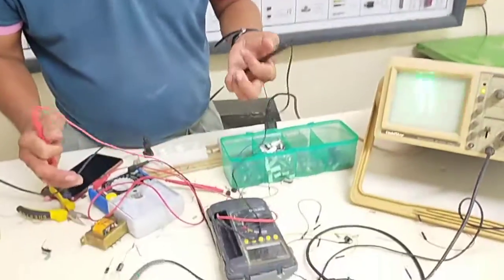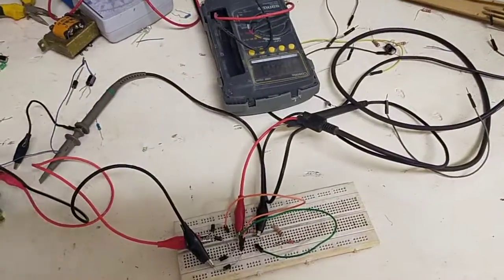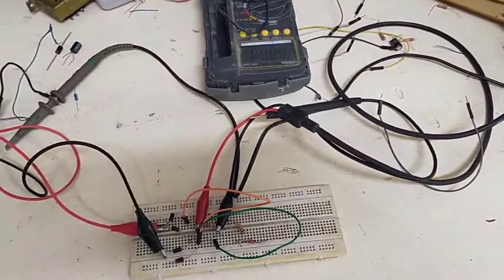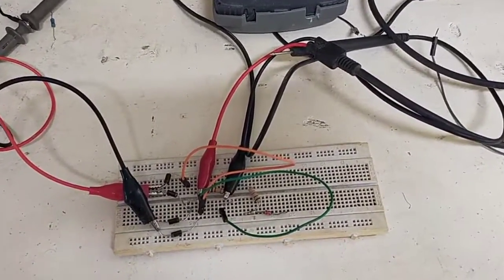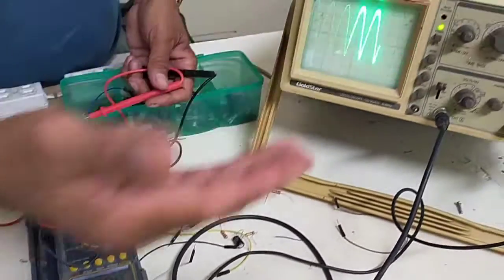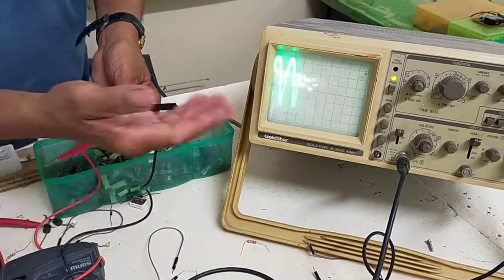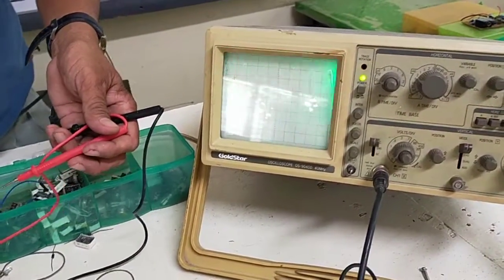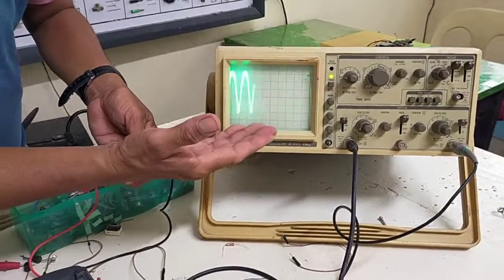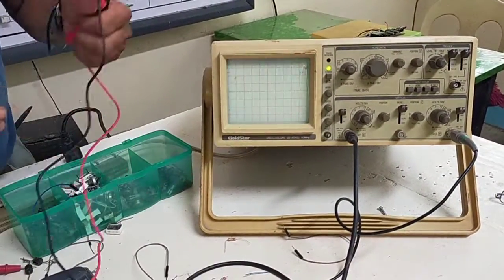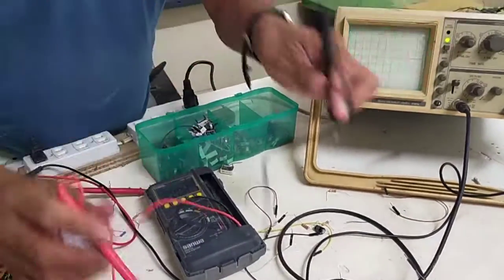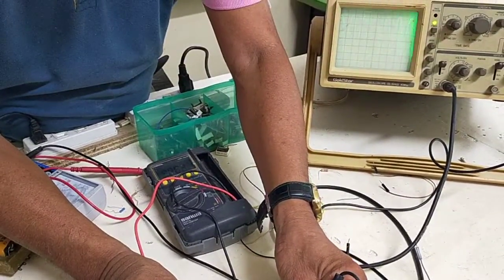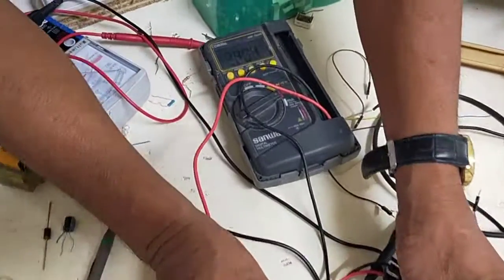Alright, let us now proceed to the last rectifier circuit, which is the full wave bridge type. We have here the output across the RL, which is the same as the full wave center tap type. It is also full wave, and the frequency is also doubled. If we are going to be sure, class, the frequency is 120 Hz. See, 120 Hz.